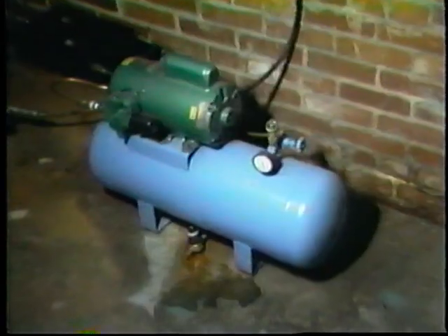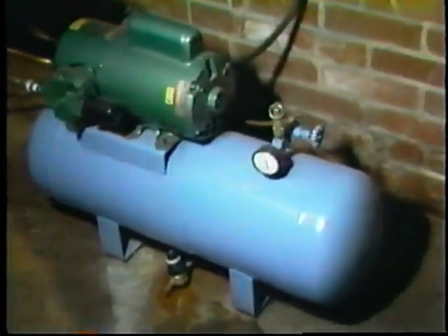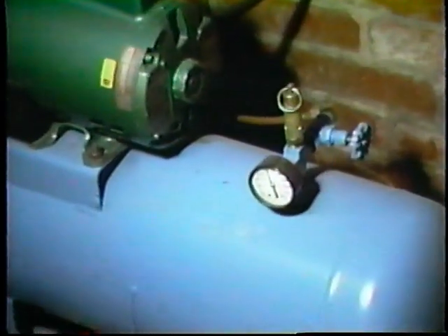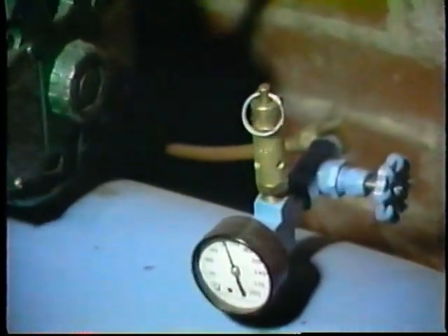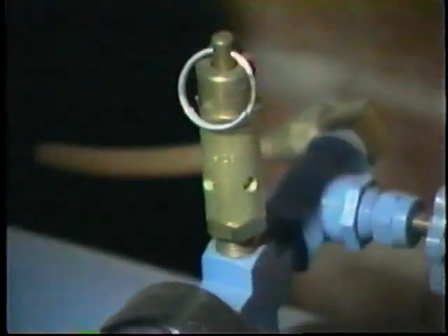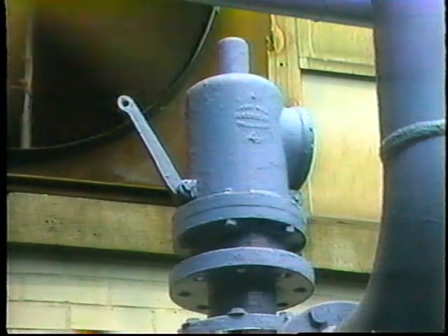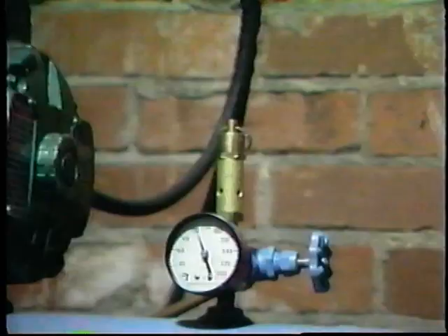As you might suspect, in most pneumatic systems, safety valves which monitor compressor output are not intended to be operated frequently. But for that one time, they have to work. It's important to know they will. That's why safety relief valves are equipped with a manual test lever. It allows an operator to regularly activate the valve manually to make sure it's not clogged or that the poppet has not become jammed in the valve body.